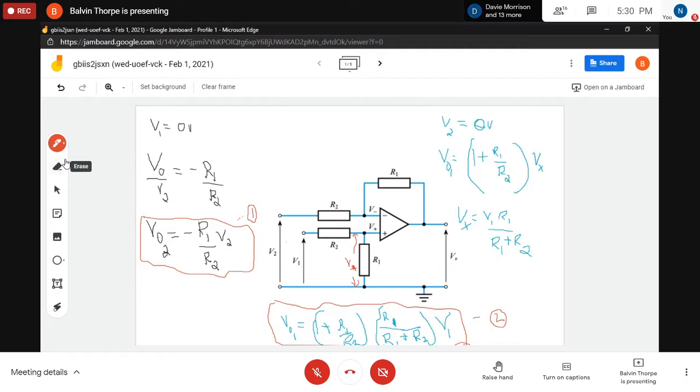All right. So in order to do that, the first thing that we're going to be doing is what you're seeing right here. We're going to ground V1. And if we ground V1, it means that our input to V1 is 0 volts, right? So we ground V1. And by grounding V1, no voltage goes on V1, which simply means that the resultant network would be an inverting amplifier.